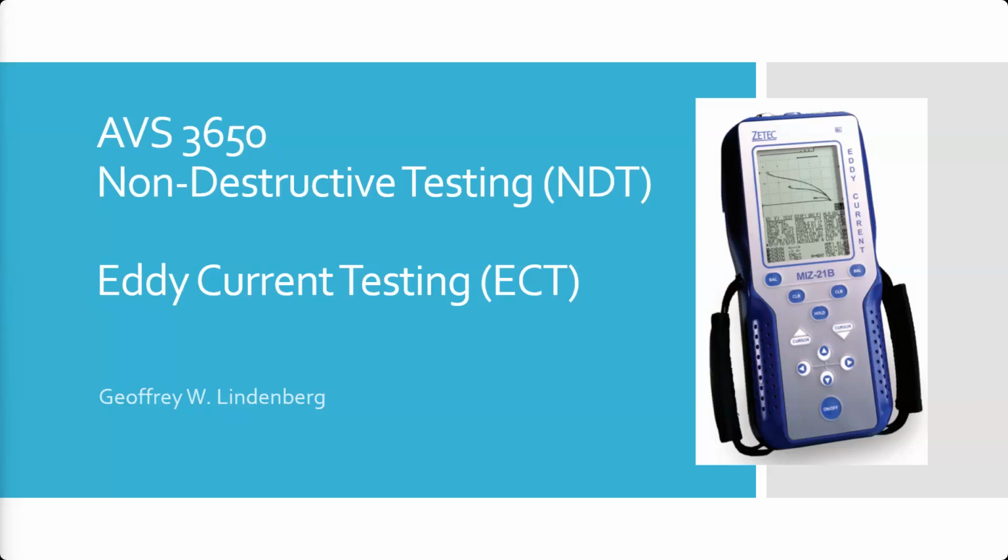For eddy current testing, as well as the others we're going to talk about after this, ultrasonic, infrared thermography, and the majority of the other techniques we're going to look at, it's going to have some kind of a readout on a display screen rather than a visual inspection. And I realize that a video scope is a display screen, but you can think of the video scope as transferring what you would see here over to here. This is not transferring the image that we have to look at. We're looking for some kind of an indication on a display screen.